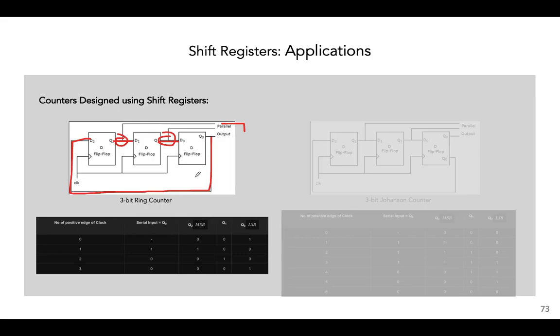All right, so let's see how this counter works. Again, everything will be controlled by the application of the clock pulses. Now, say that initially in your register the data is 001. This is your data initially, right? 001. When the next clock pulse arrives, this one, which is at this point, at the third flip-flop, will go out, but it's not going out of the register.